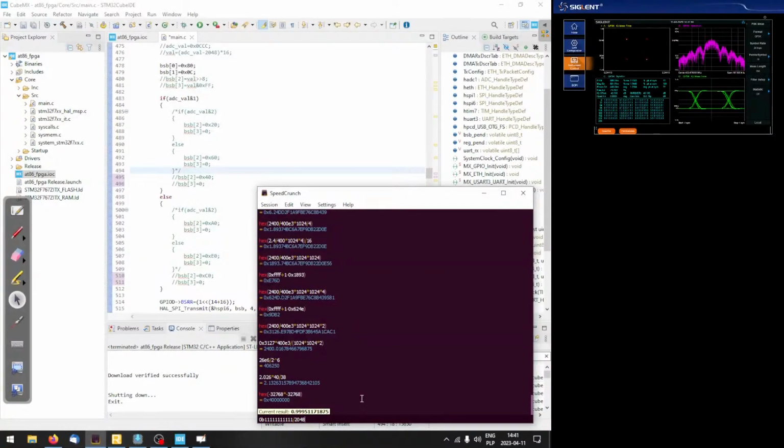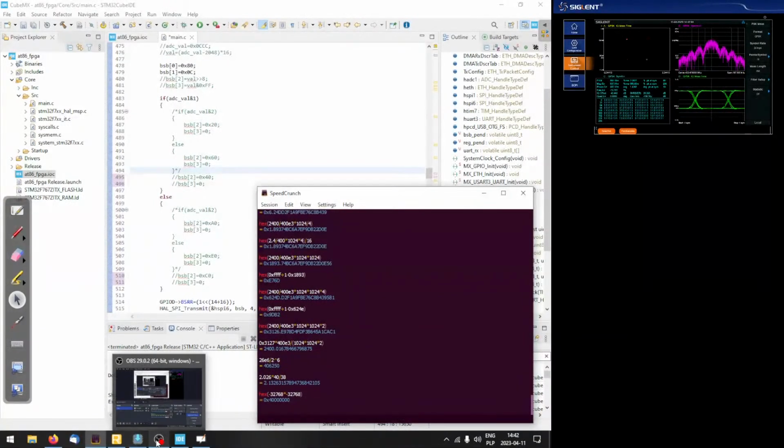So basically, we've got signal that is in this range, and we want the constellation points to be not at the edges, because when we apply filtering, we've got some overshoot resulting in the signal. So we need to have some overhead for the overshoot in the signal.